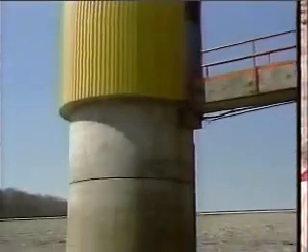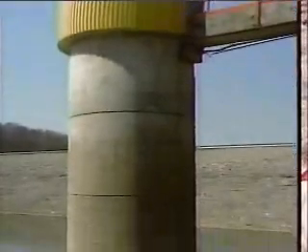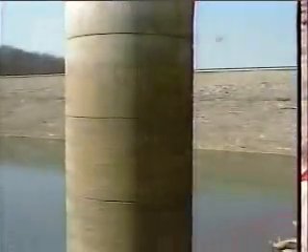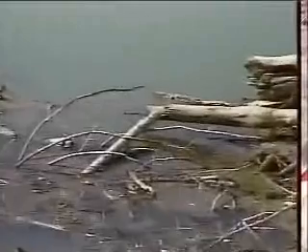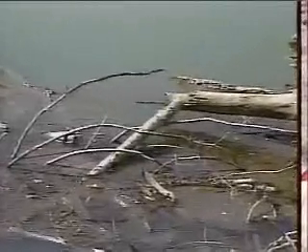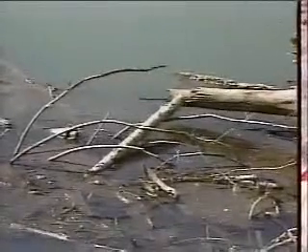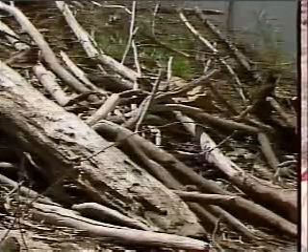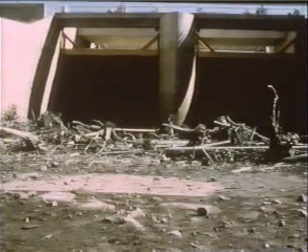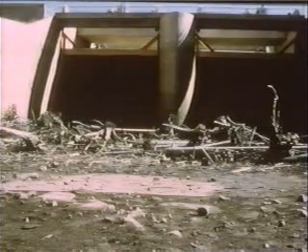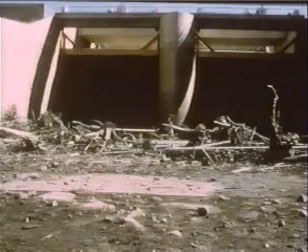Now, let's talk about problems related to debris. Debris is usually seen as floating trees or limbs. The collection of debris on or around the dam isn't an immediate danger. However, it could lead to serious problems. You see, debris can collect and block outlet works and spillways. It can become waterlogged, sink, and block the intakes of water conveyance structures. And if a flood occurs when debris is blocking water conveyance structures, the dam could be overtopped.